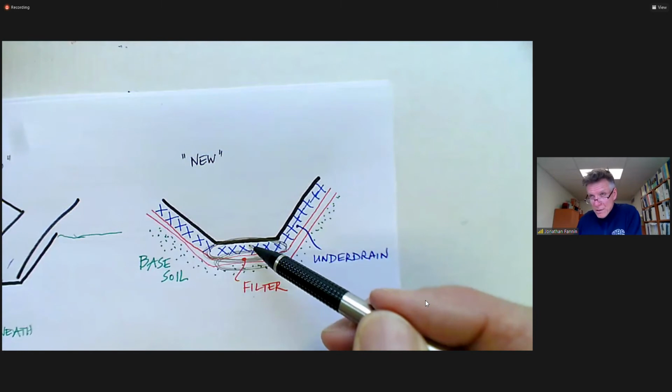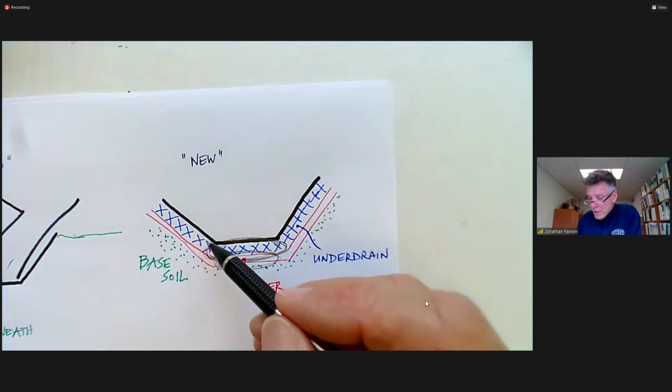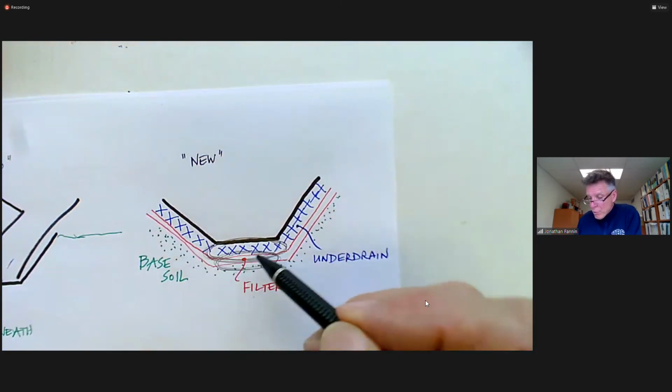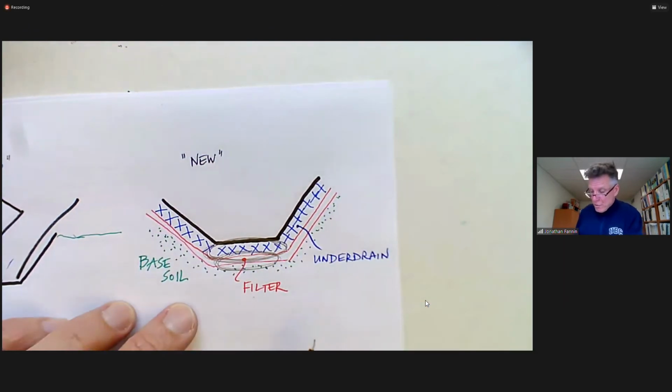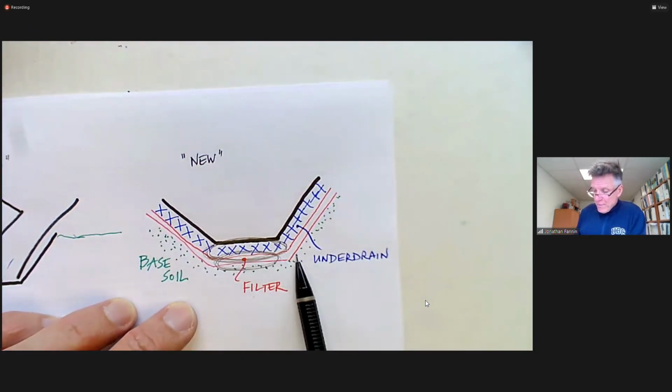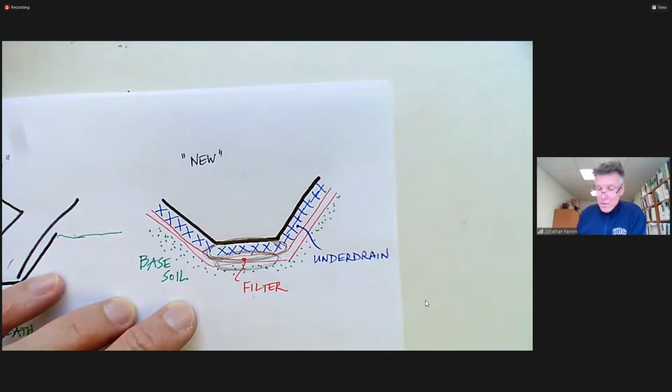The under drain does its job, and we don't have unacceptable pore pressures building up during occasions on which the spillway is being used, nor do we have unacceptable inflows into it and or clogging of the drain and or erosion beneath it.